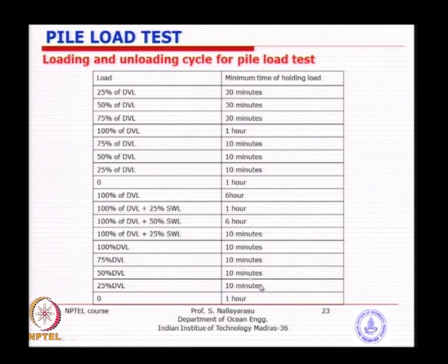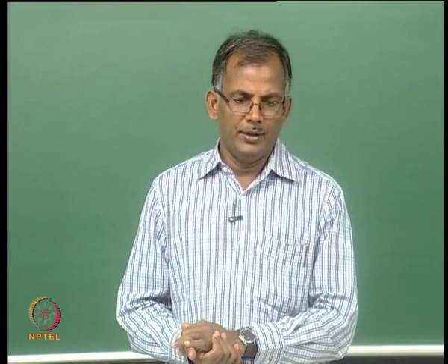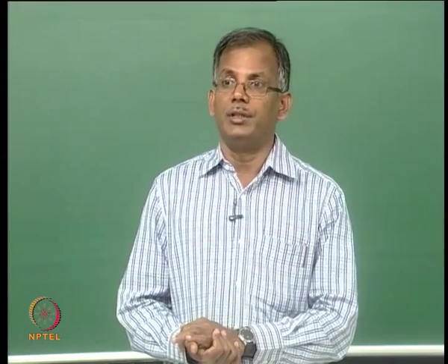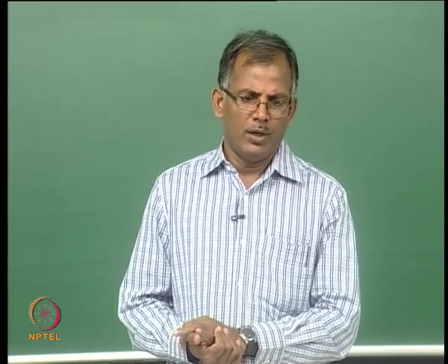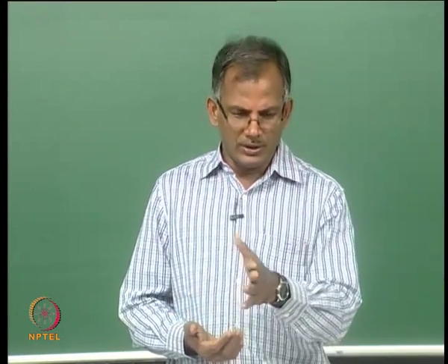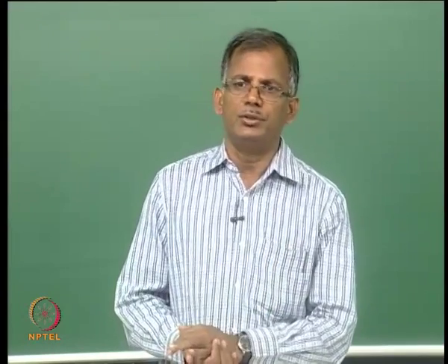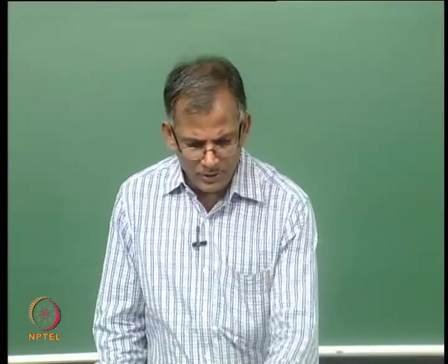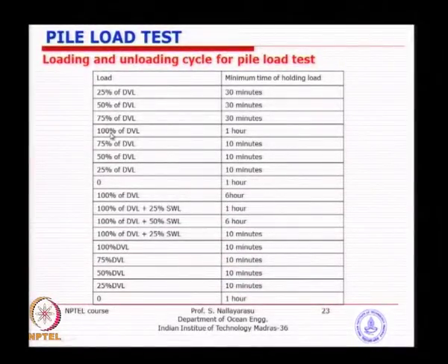So basically this is just a typical time versus increment of load. I have just taken it from the manual of pile load testing from the Association of Civil Engineering Contractors. Everywhere they use this, but if you look at IS codes, they may actually give you slightly different numbers and different timing, depending on which jurisdiction you want to use.